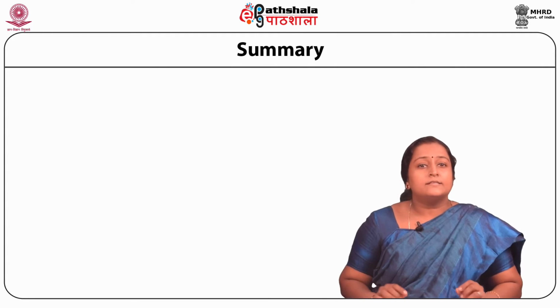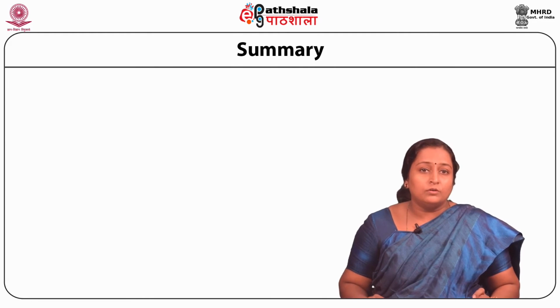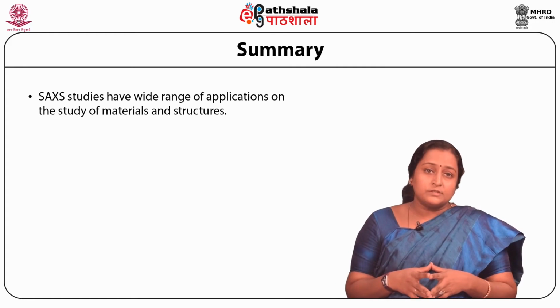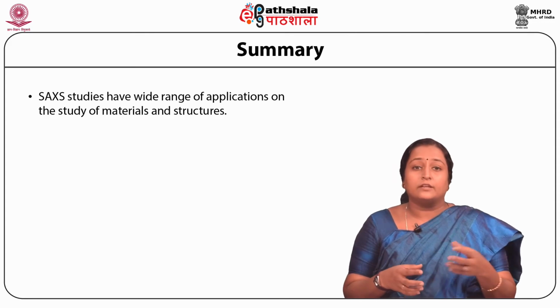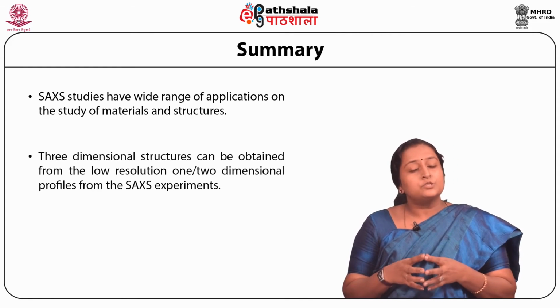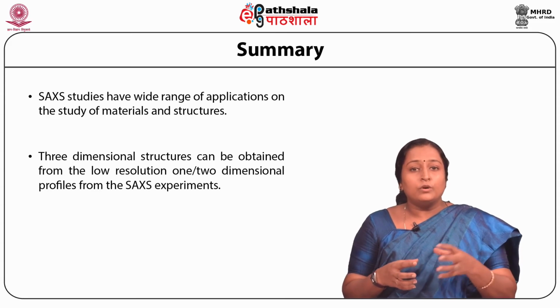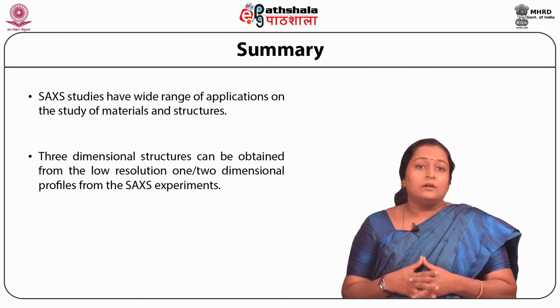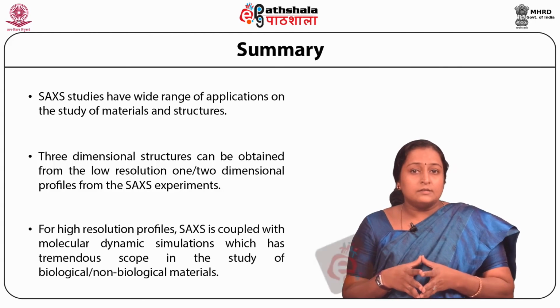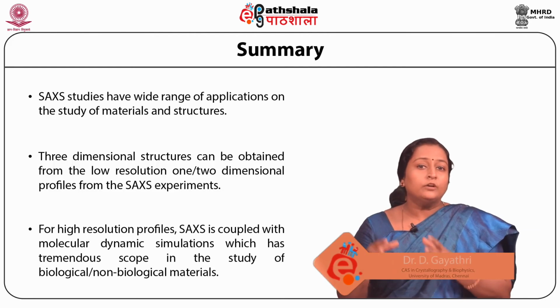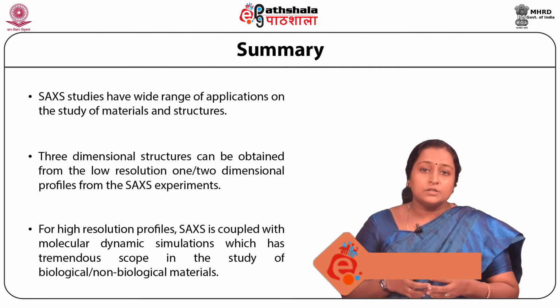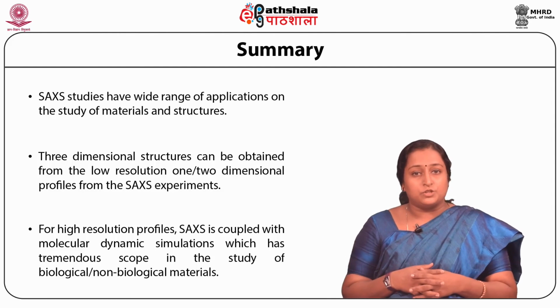So students, let's summarize what we have learnt in this module on small angle X-ray scattering. We saw that small angle X-ray scattering has a wide range of applications in the study of materials and their structures. Three-dimensional structures can be obtained from low resolution 1 or 2-dimensional profiles from SAXS experiments. For higher resolution profiles, SAXS is coupled with molecular dynamic simulation, which has tremendous scope in the study of biological and also non-biological materials.